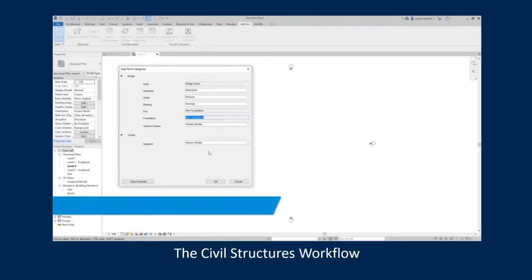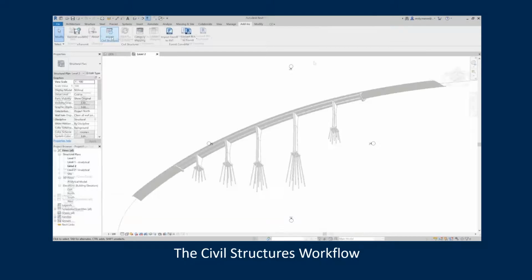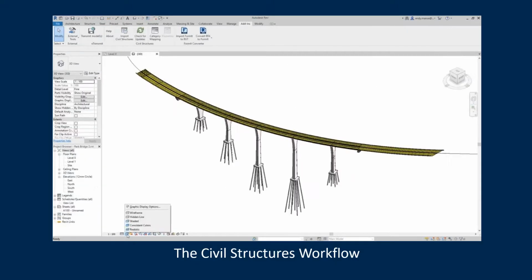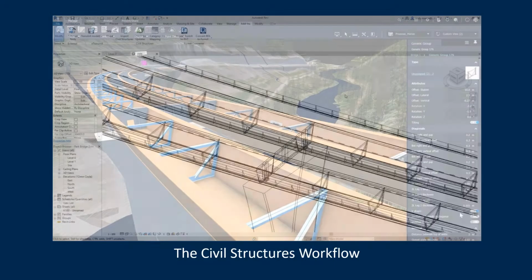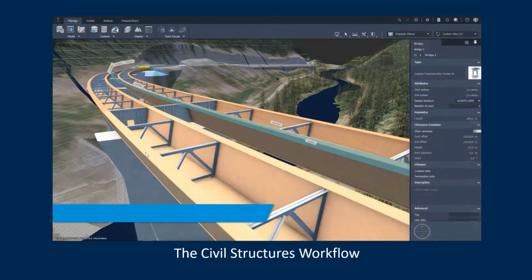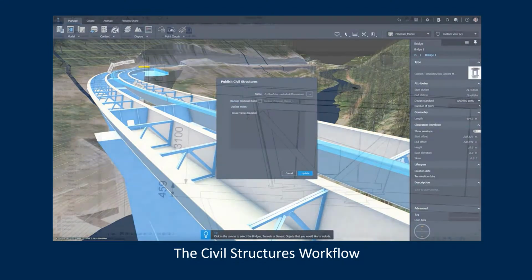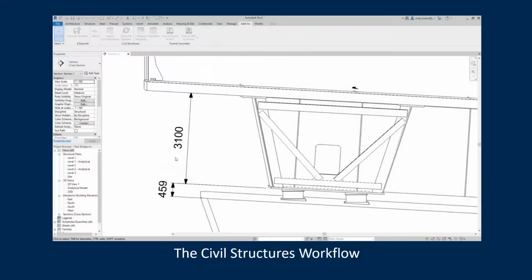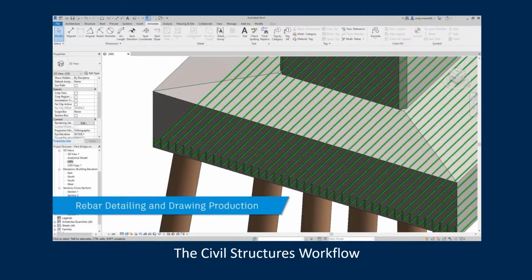You're simply mapping the properties as you can see here. And once we import that, this is the result, where you could actually see the detailed parametric nature of the bridge in Revit. Now, what if there were any changes? So let's say you did a change in Infraworks, or maybe the corridor updated, you will get an alert in Revit to apply the update. So can you see how connected this is?